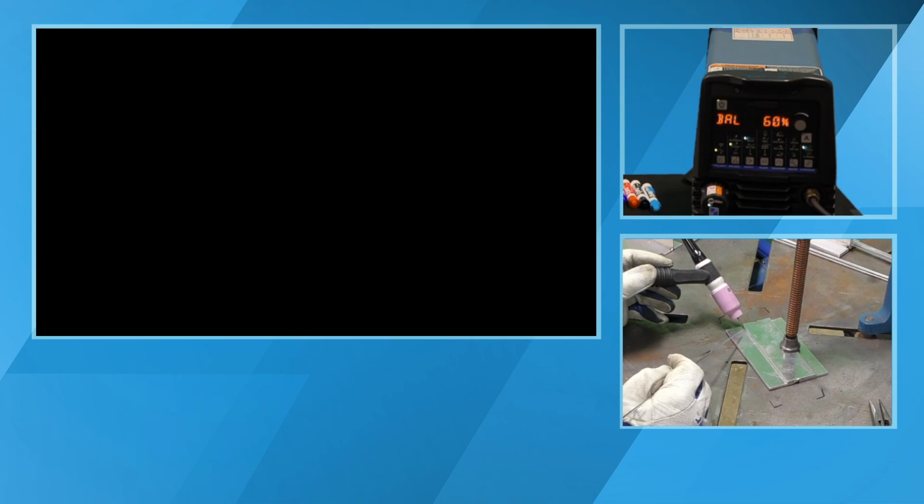It's not real clean stuff, but what we do want to look at is the cleanliness of the puddle. Hopefully you guys will be able to see as I weld along, there's not going to be any of that black oxides floating in the puddle. I'm going to weld about a couple inches across here. I'm going to stop. I'm going to change my balance setting up, which I'll explain. I'll probably go up to about a 95% balance setting. And then you'll be able to hopefully see some of those black oxides forming in the weld puddle and see what I'm talking about here.